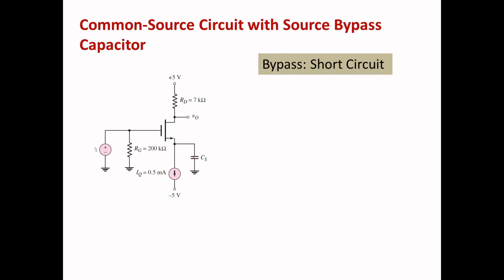So you can try in lab. If you connect a capacitor like 100 microfarad or something, here the noise will be bypassed and gain will be enhanced to more. If this is not connected, stability may be good, but your gain will be very less.